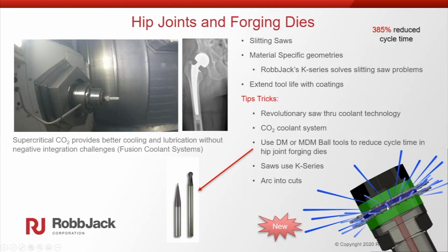You know, then we have like the thru-coolant saw solution that we're going to talk about more, where we're able to get ports on both sides of the saw. If you gang them or just one saw, you're able to do that. That's a pretty dramatic improvement on performance and quality, because getting the coolant on both sides of the saw equally has always been a challenge with external types of coolant sources.